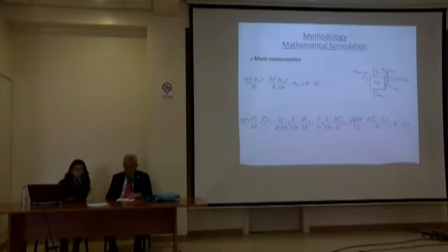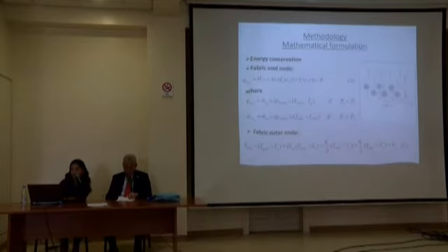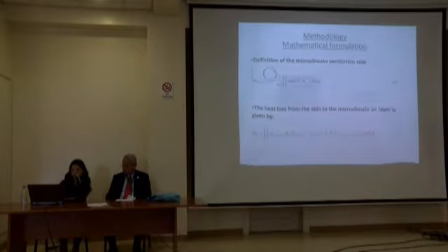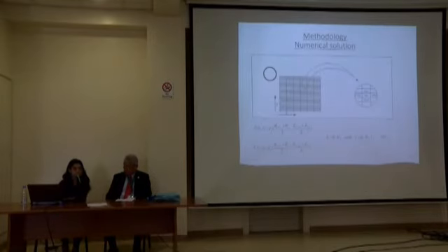Then we will get the temperature from the energy equation after calculating the pressure. Another time we will get the temperature and then recalculate the pressure. These iterations will be repeated until convergence of temperature and pressure. The convergence took 300 iterations and about 30 seconds for each segment.